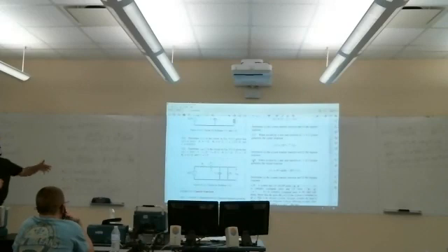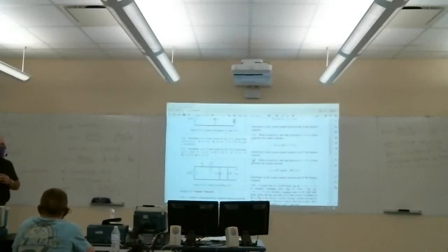The impulse response completely describes the system. If we know the poles and zeros of the transfer function, we can get the transfer function, so the poles and zeros also completely describe the system. And there's one more way. If we know the input and output for any input, we can actually get the transfer function, the impulse response, the differential equation, all of that.